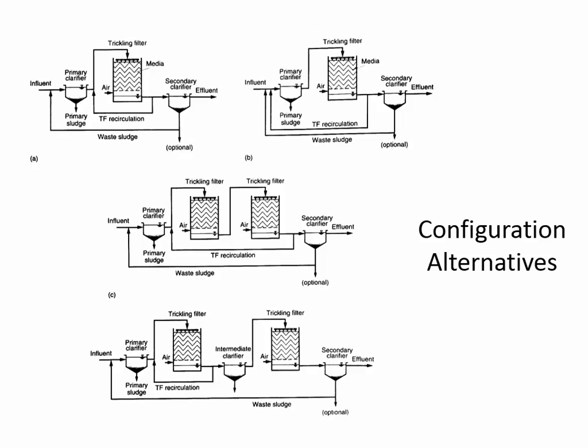So look at these different alternatives of configuration. In the first, you can see that there's recirculation of the water, and there's going to be a little bit of a slime layer in here because when the particles slough, the water's moving through the bottom of the filter into the pipe. So what's recirculated will have a little bit of slime layer in it, but it hasn't been concentrated before it gets there.